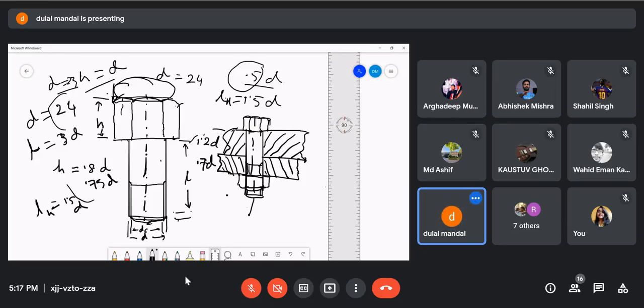I appreciate. Sir, the point where you've written D and DC, you said that the lower edge is somewhat pointed type. The diameter is somewhat less. In some cases you will find it is somewhat round shape. Why is it so? It depends. Suppose you are inserting this bolt where the clearance is very less. In that case you need to have this kind of somewhat round shape. The very special case. Normally you will find it this type.